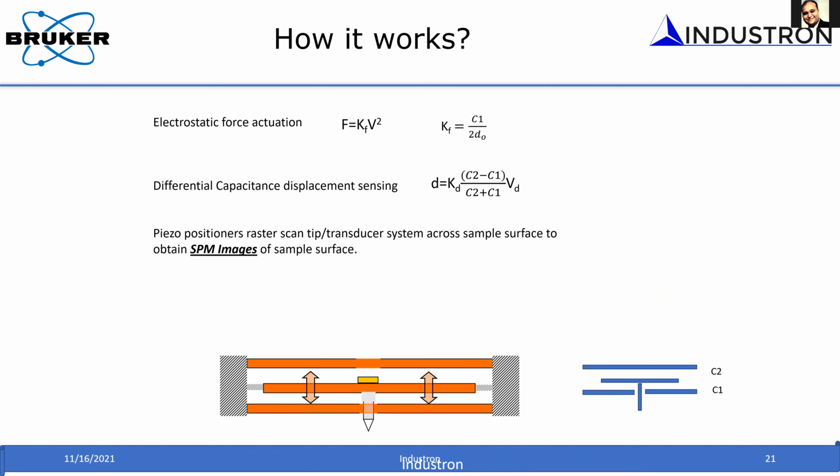So how is it done? There are many ways of doing nanoindentation experiments. What you need is a transducer to apply force and measure displacement. There are ways that you can use physics. For example, you apply a current through a coil in a magnetic field, and you generate force. That is one way of generating force. And if you have a capacitance-based sensor, you can measure the displacement. By combining the various ways of actuating and measuring the displacement, you can have different types of transducer.